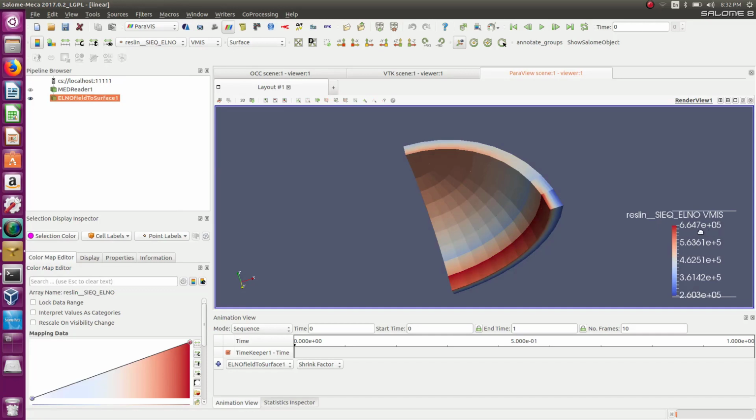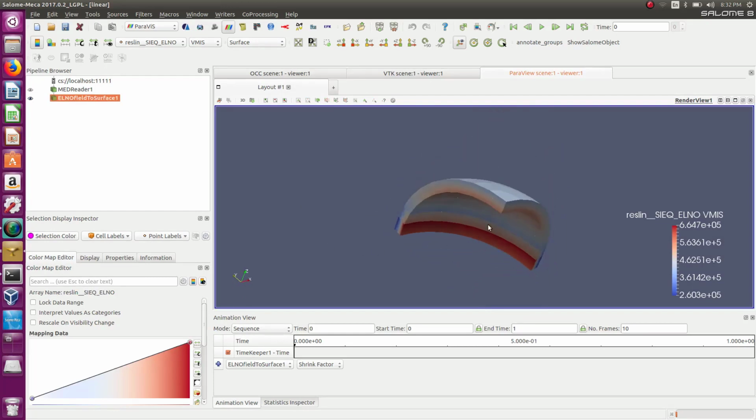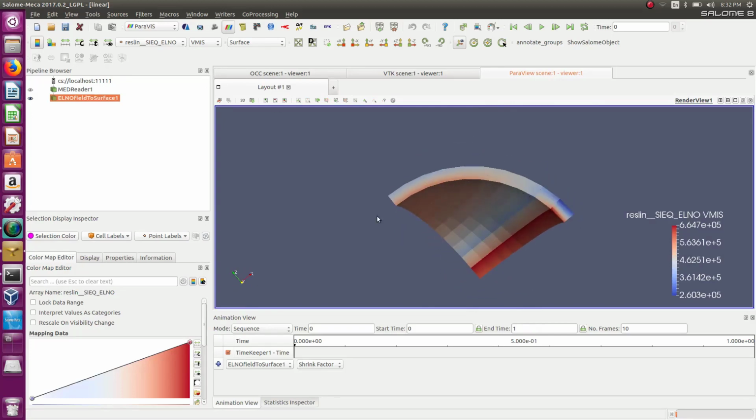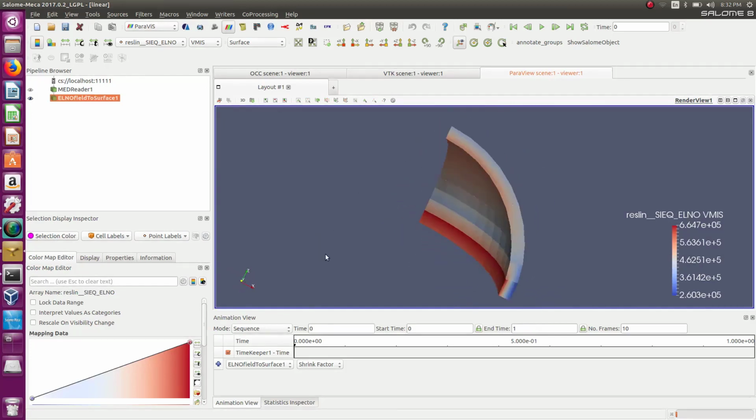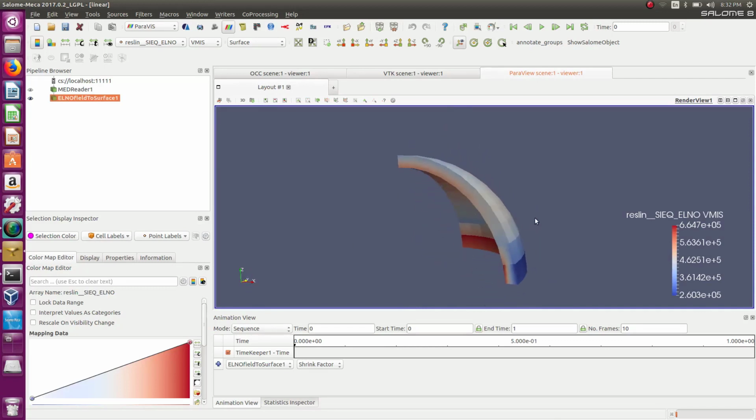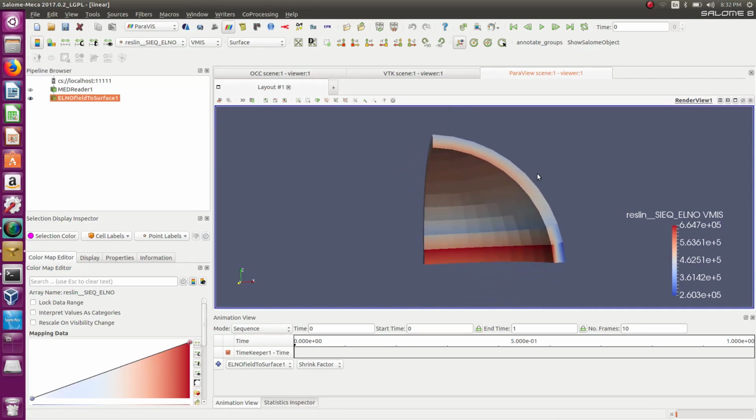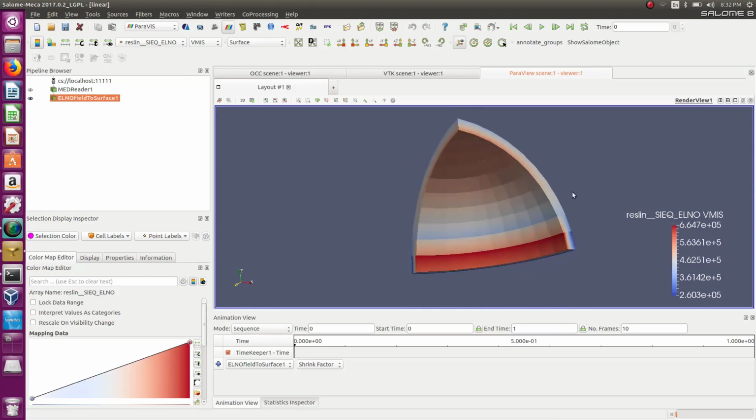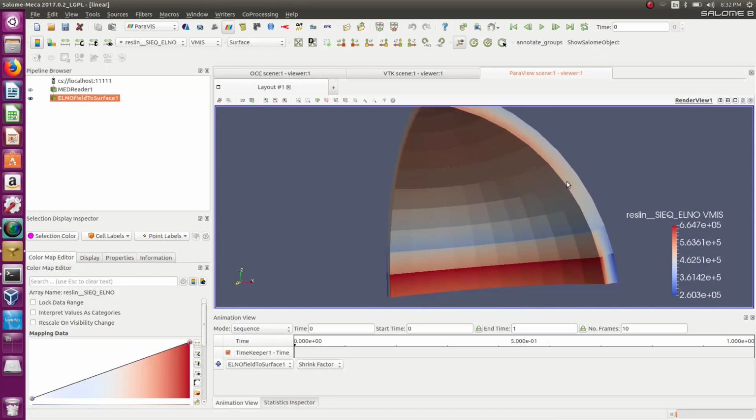Okay, I'm getting something around 664, so I think I have a huge stress here around this edge. So I don't know, maybe it's over-constraint of the model in this area. But anyway, that's to show you how it works. So now the model works basically. So let's see how I can extract and linearize this on this area, on the thickness.